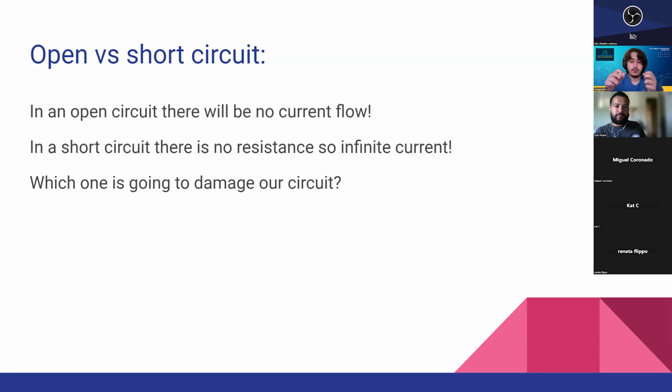There's a chance that you put, let's say 5 volts, but your battery can discharge up to 2 amps, right? So then your resistor is going to get really hot and it's going to start burning, right? Or maybe your wires are not even capable of handling that much current. So your wires are going to actually start smoking, right? So this is a really important topic in basically any electrical engineering, any power electronics or anything. Any questions? All good?